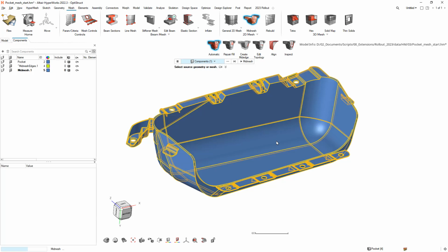So if I split the CAD surface, the FE geometry will follow it. And also mesh selections are a lot easier. So selecting by surface becomes inherent in the fact that it exists as both CAD and FE. So I've shown stitch and split, but also tools like drag, extend, imprint, and ruled can all be used directly on FE geometry as well.